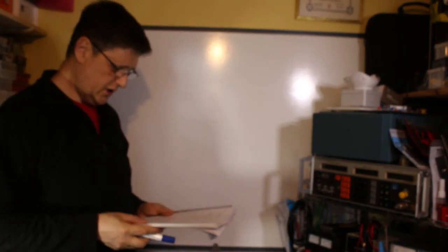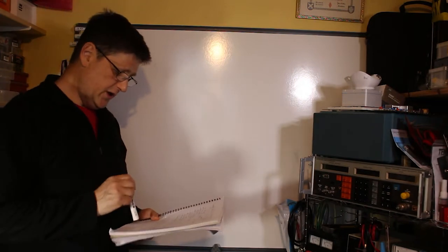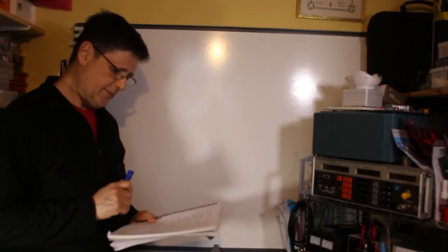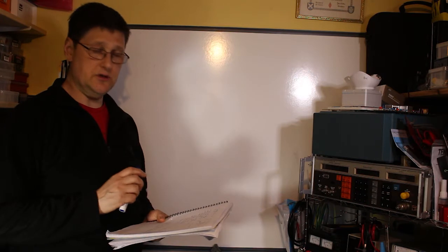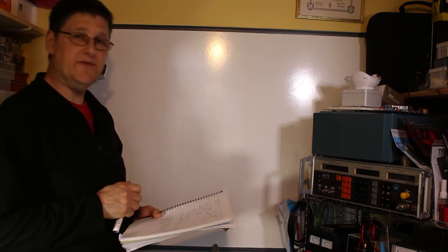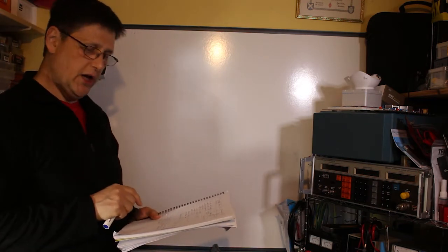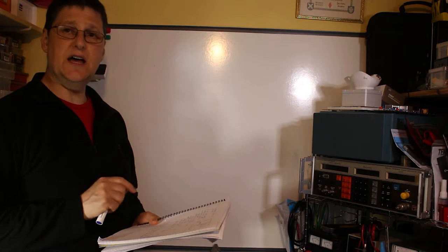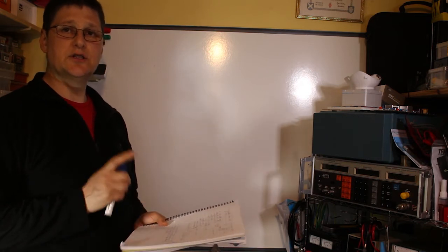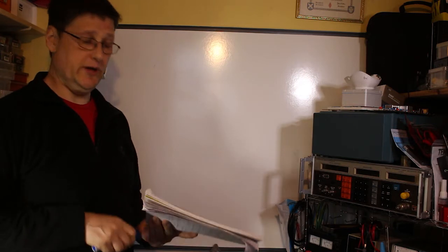And the question that Martin has asked, and he put it up in the WhatsApp group, is: the transistor in the diagram has a current gain, which is known as beta, of 200 and a base current of 10 microamps. What is the resistance of R1 to get a voltage of 6 volts at the collector of the transistor? So I think the first thing we need to do is get a diagram going here.